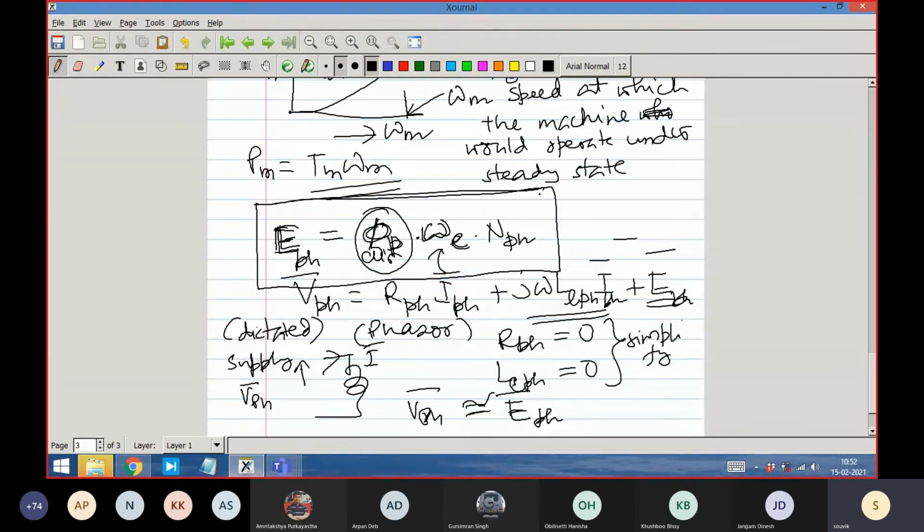So therefore we see that when V phase is given, what we are essentially making constant is the air gap flux. This phi p, suffix p is for pole, flux per pole. Your professor must have done the expression for that. The flux per pole comes in the derivation because the machine may have more than 2 poles. That is unnecessary complication at this point. These are just multiplying coefficients. You can handle that. That is not a big deal.